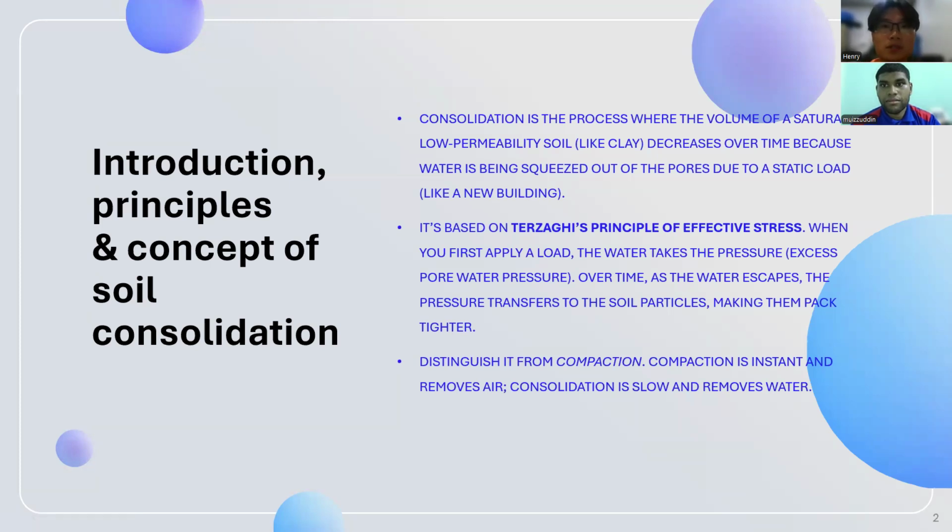So the first is, consolidation is the process where the volume of a saturated low permeability soil like clay decreases over time because water is being squeezed out of the pores due to a static load like a new building. And it is based on Terzaghi's principle of effective stress.